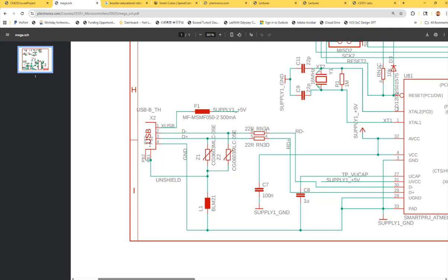Once you click that button, a layout window pops up, and you never want to close one of them while you are modifying the other one. For example, once you get a layout window, you are not thinking you are going to modify it, so you close that layout window. And then you come back to the schematic and start modifying it further.